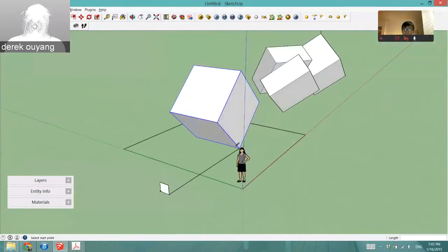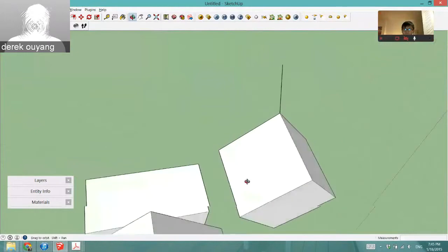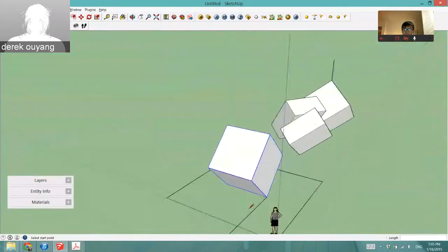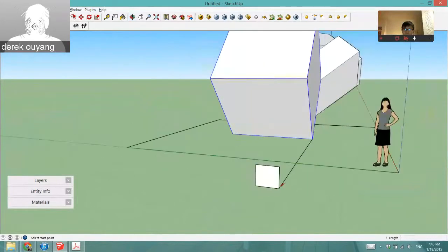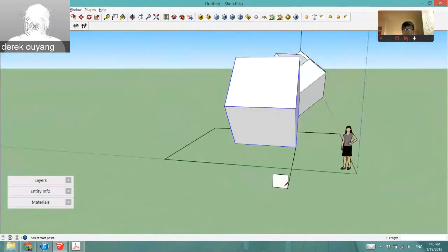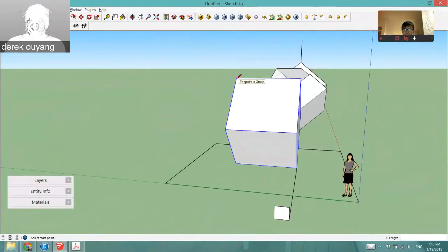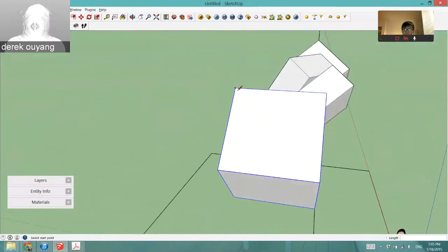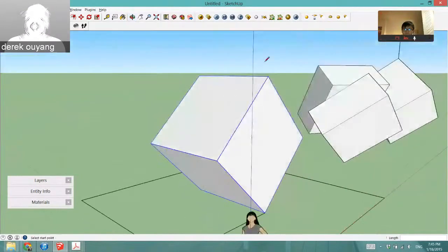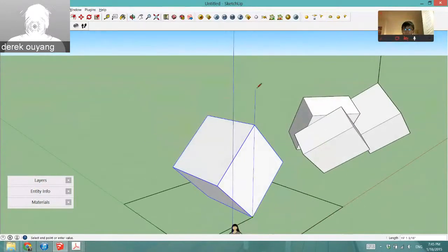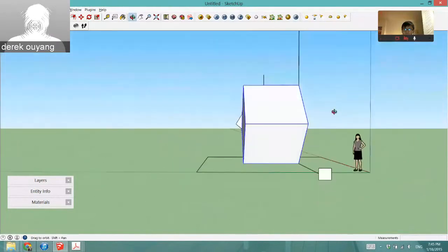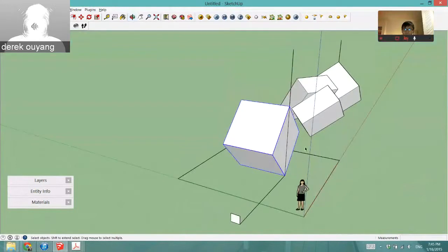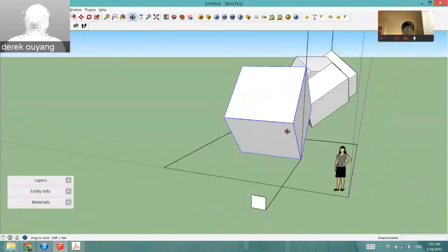One more thing is simply going to be this line we had created before, because it's going to be hard to know exactly what rotation to make once you've gotten the correct plane. But if you can just imagine pinching this corner once we get to that rotation and just pinching it up over onto the guide line, which would be just like this. And we don't have to type in a dimension, we just simply have to snap on to a guide line. So this is all we need to do the complex rotation we need.